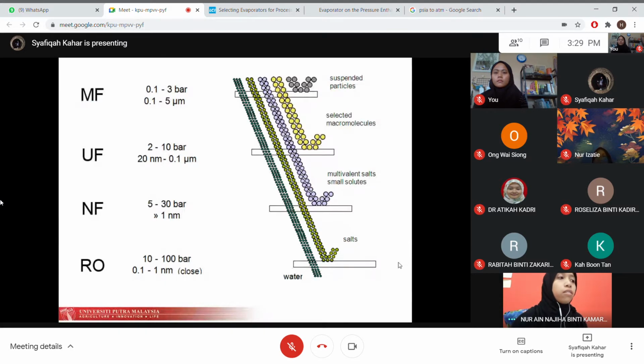Okay, so for ultrafiltration, suspended solids and solids of high molecular weight are retained in the so-called retentate, while water and low molecular weight solids pass through the membrane in the filtrate. This separation process is used in industry and research for purifying and concentrating macromolecular solutions, especially protein solutions. In this process, we want to filter protein, alpha amylase, and also alpha glucosidase.